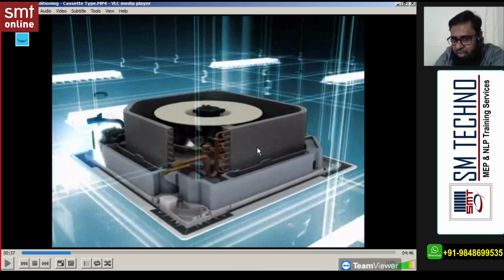Okay. And on this coil, condensation will take place. So at the bottom, you'll find the passage, the drain tray, so the water will collect. But remember, this unit we are installing in the false ceiling, so we cannot take the PVC pipe below the false ceiling level. It's not allowed, because if you run the PVC pipe below the false ceiling, the client or the interior designer will not accept.